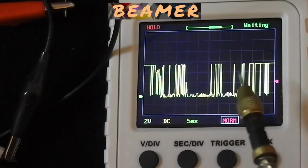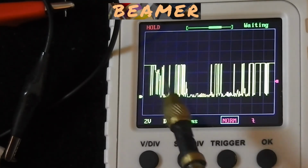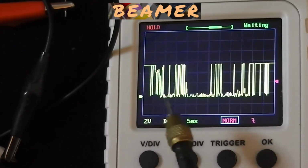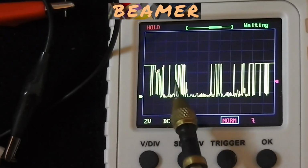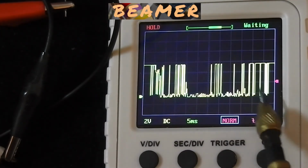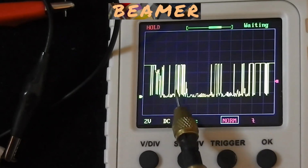So if this switch is being constantly polled, how does the CPU know whether the switch is truly turned off from being turned on, or the other way around? Because there are so many noughts and ones, so many ons and offs here, that unless you apply particular software conditioning, the CPU is going to go berserk.